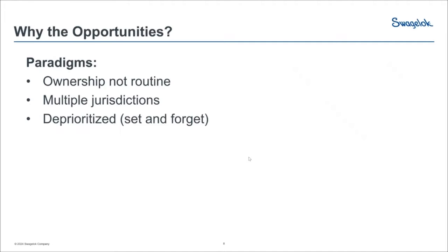There's a mindset of set it and forget it, whereas with these systems, it's paramount that they enjoy regular preventative maintenance. Or lastly, what we tend to see is that a lot of times these systems are constantly changing. Temporary becomes the new permanent. Your process and instrumentation diagrams and mechanical prints don't keep up with the actual.